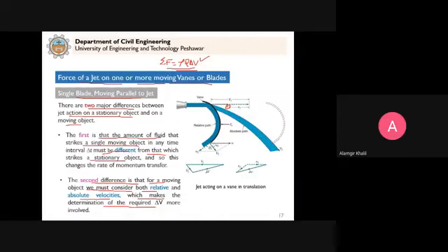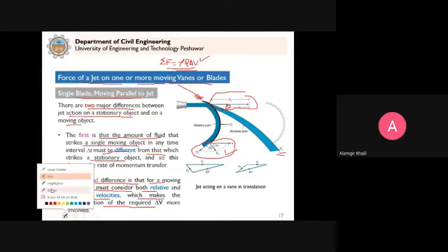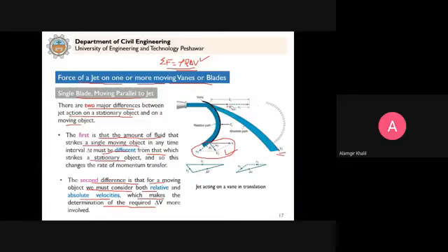So that's why we show the relative velocity, relative path, absolute velocity, absolute path here. And this triangle you consider in calculation of the forces. This one here, the jet enters horizontally, so that's why there is no triangle. But it can enter horizontally at an angle. Then in that case, we will have a triangle similar to this one, a more complex case. But now the fluid enters horizontally, so the inlet velocity diagram is easy. But at the exit, we have this triangle here.